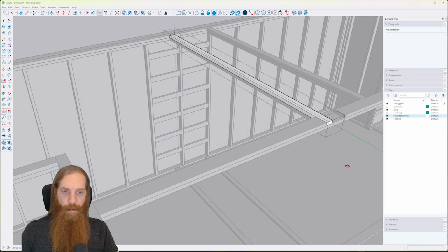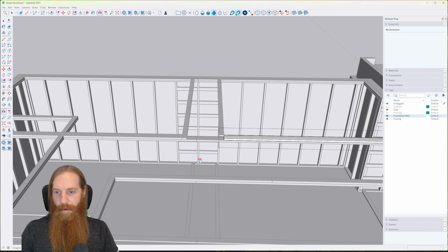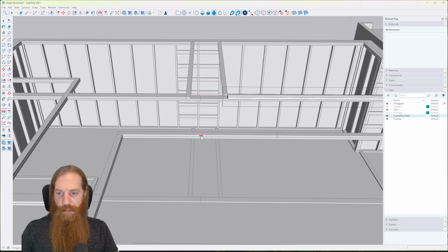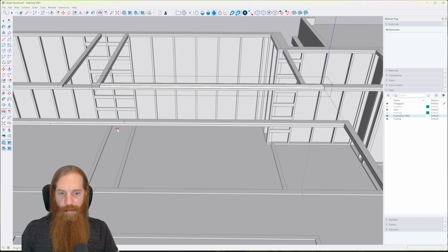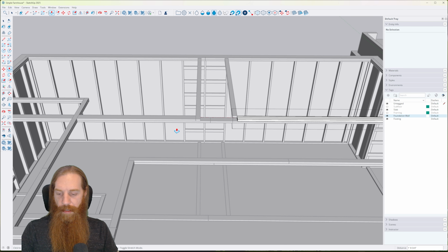Actually, I guess that's fine. Well, no, because you have the seam right there under it. What I would actually do there is change where that seam is in the plates, which would require putting in another board in the middle there.